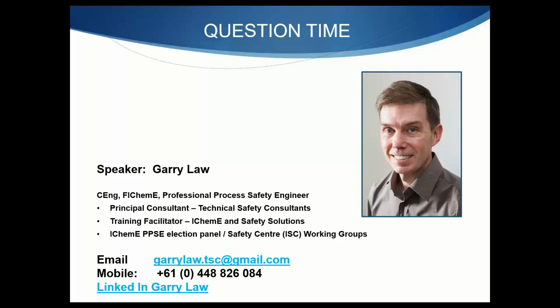Well, I showed you one with DP cells, and it just depends what you're using on site. But the main thing with foam is that there's probably 2 or 3 different levels you're interested in, and the foam will probably be the thing on the top. If it's a stabilized foam, then you probably can't see the foam itself because it's a lot less dense than the actual liquids. So you'd need to make sure that the top level of whichever liquid is on top, say hydrocarbon on top of water or on top of an acid, you'd be measuring that and making sure it's well below the top nozzle so that the foam doesn't get up there. I've even seen some places where the foam almost solidifies immediately as it goes over the top, and then it blocks your overflow line or your vent line, and then you're getting overpressures as well as overfill. So it's very important to keep those levels down well within the vessel and make sure you oversize the vessel accordingly.